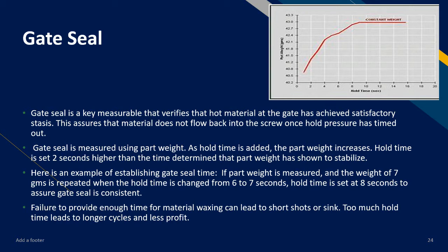If you look at the chart up above, in this comparison between 10 and 12, there's consistent weight. So you'd be best to set the hold time at 12 seconds.